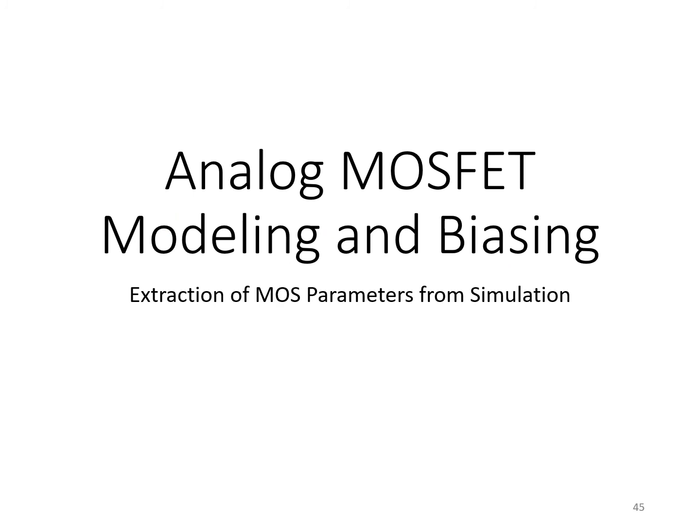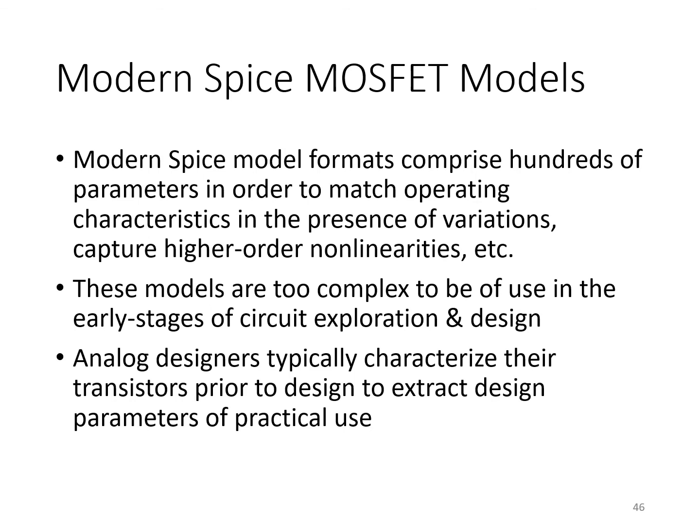So I mentioned in the past that it can be really useful to do some pipe cleaning simulations when you're starting design, especially in a new technology. And just to get familiar with your transistors, you really want to know your transistors when you're starting a design so that you can quickly, on the back of an envelope, make estimates and trade-offs and calculate rough device sizes. So I just show you here examples of some simulations you can perform on transistors to help you get comfortable with them and extract some of these model parameters.